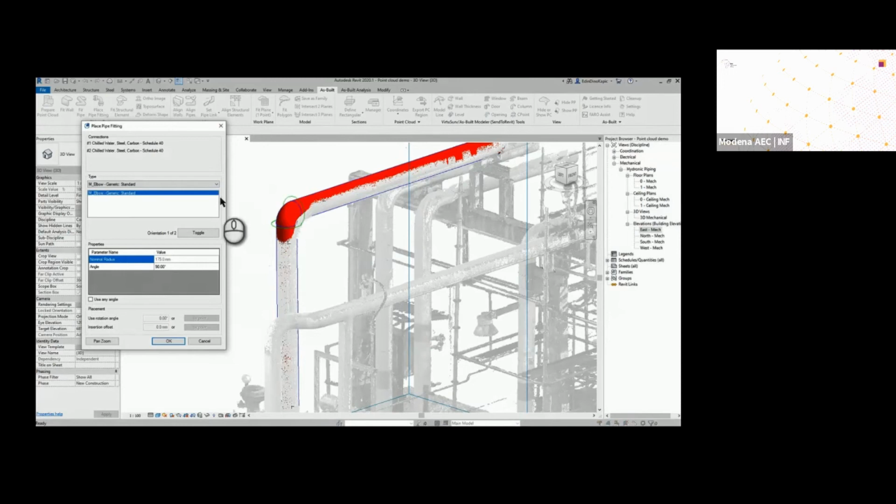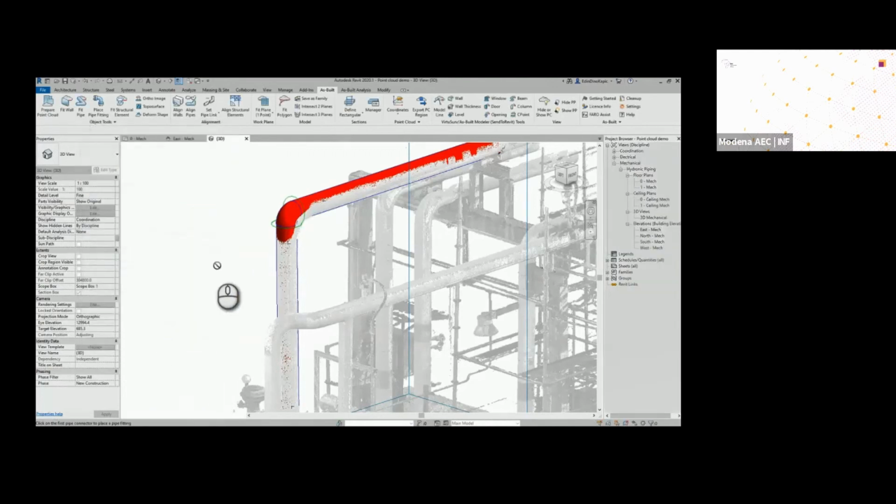The idea is that AsBuilt is utilizing all the family components that I have loaded in. So the more components I load in, the better the outcome for my elbow design. As you can see, I'm simply using generic object. But you can also use carbon steel press fittings, PVC items, steel flanged items, whatever the case is, whatever you have created in Revit, utilize it within your point cloud project. And again, allow for AsBuilt to use the same items. From here, I simply press OK.